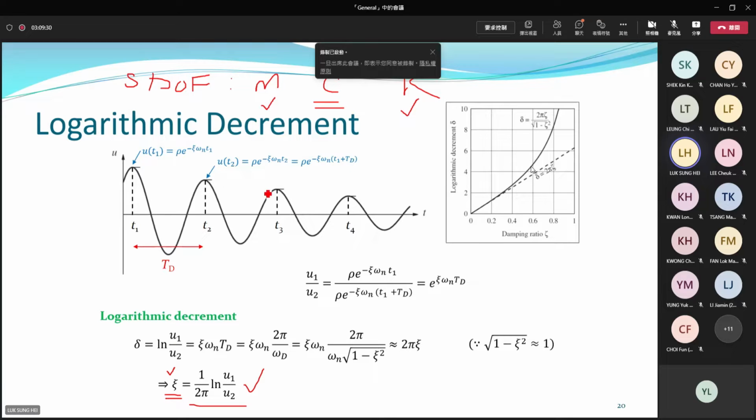You can calculate damping using the displacement response. You can do an experiment in the lab: record the displacement history of a system over a few vibrations, and then, based on your displacement record, using two arbitrary vibration amplitudes, you can calculate the damping ratio, just like here.